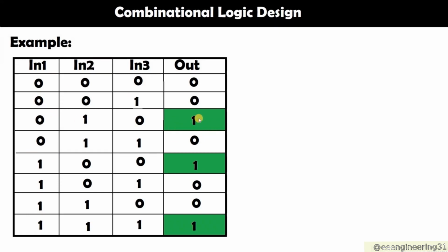And then you have figured out that you have 3 of these cases where your output is 1. So what do you do? You create an OR gate with the number of cases where you have an output of 1. So this is my OR right here, and I have 3 cases right here, right? So I will have an OR gate with 1, 2, 3 inputs.